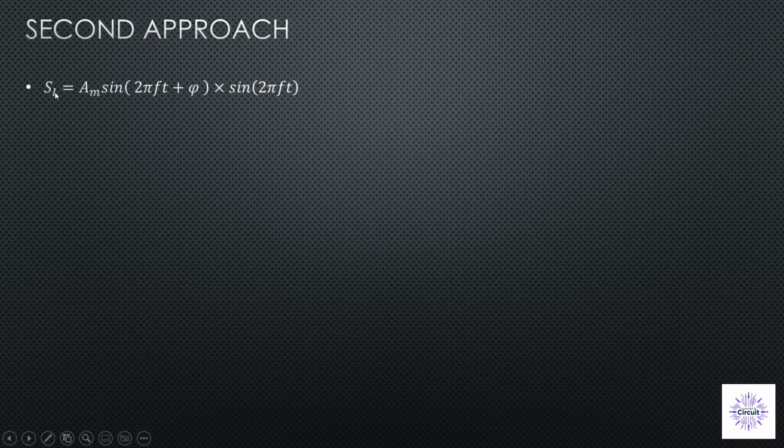We define SI equal to our signal multiplied by sine of 2 pi ft, f equal to the frequency of our desired signal, right? The frequency of our received signal. We basically lock the sine wave frequency to our received frequency.